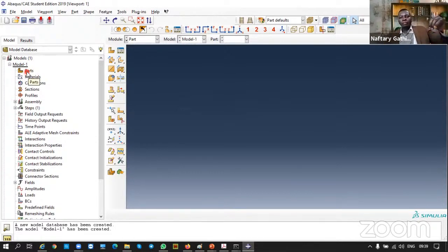Remember the same way we said for finite element analysis, we start with selecting the element type, you discretize. There was a certain procedure for all the examples that we covered. Even here in modeling, you create different parts. Then you have to define the material for different parts. Maybe you have a composite structure, where maybe a concrete and the steel decking. So you have to define for different parts what are the materials. For the different sections, you have to define a section like a steel section, and the concrete section, and then assembly is when you bring them together to make the structures work as one.